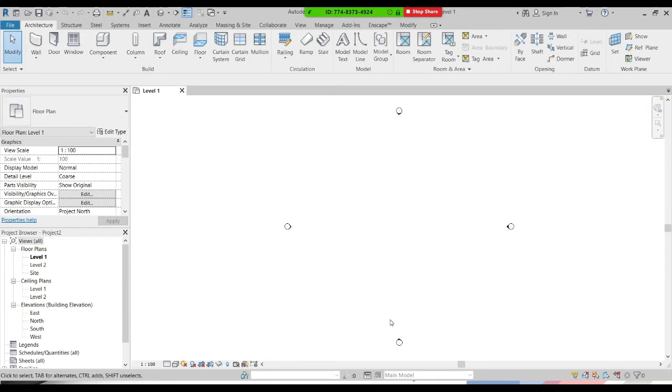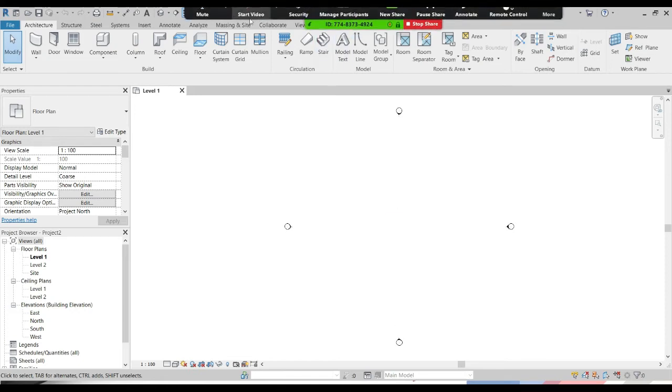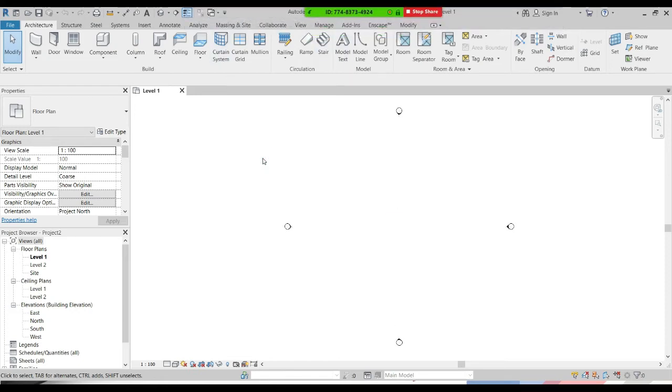So for me that I have inches, and that's how I should change it from inches to metric system, by changing the template. Well, there is another option that you can use, but it will fix your issue temporarily. It doesn't fix the whole issue. Every time I open a new file, I should do that procedure. Open the right template I want to use.